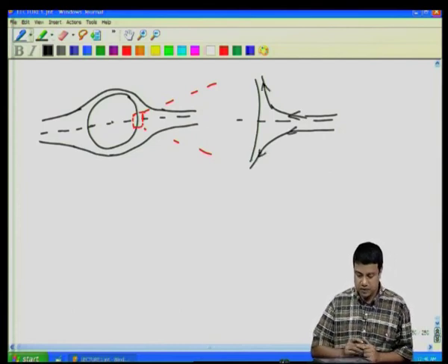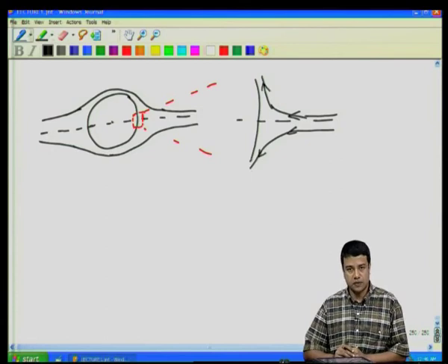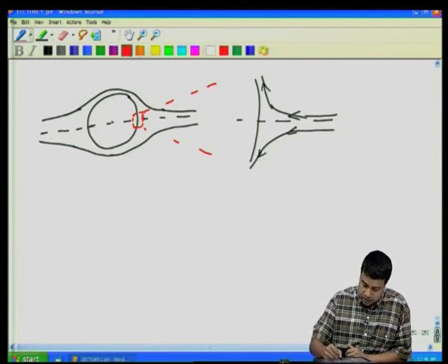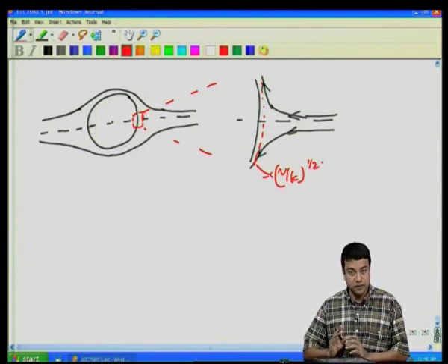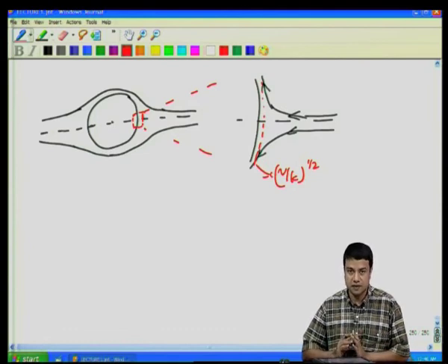So, in 2 dimensions this looks very much like a stagnation point flow. For this stagnation point flow, I have a thin boundary layer of thickness here, which goes as nu by k to the half. For this configuration to approximate the flow past a flat surface, I require that this boundary layer thickness be very much smaller than the radius of curvature.